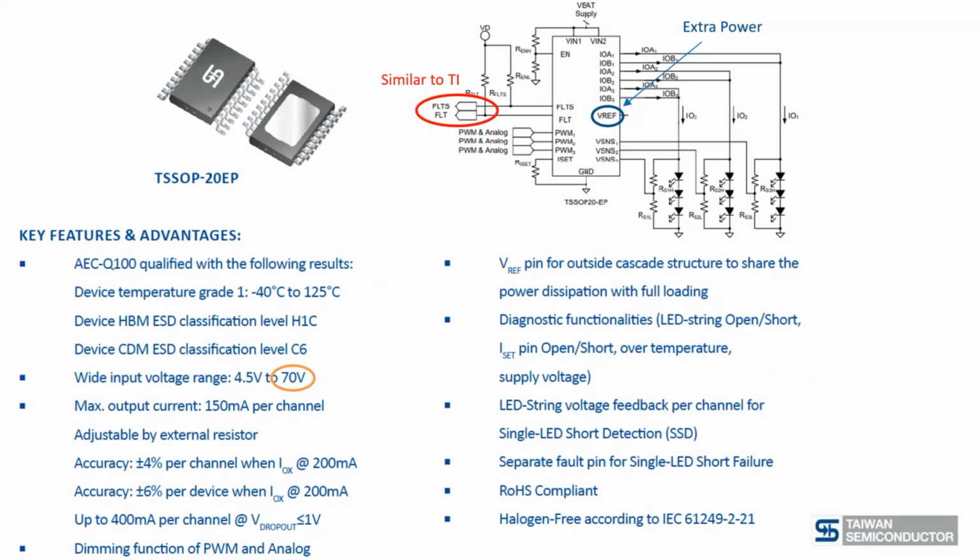Default FLT and FLTS flags are a little bit different, and here they are similar to TI. So we've got a couple of TI devices here that we'll mention later on. The way you give the fault diagnostics back to whatever device it interfaces with is done in a similar way to Texas Instruments. I'll mention the part names of TI later on in detail. And the part obviously has an enable pin that you would expect from an automotive device, so you can put it in shutdown. It's AEC-Q100 qualified.